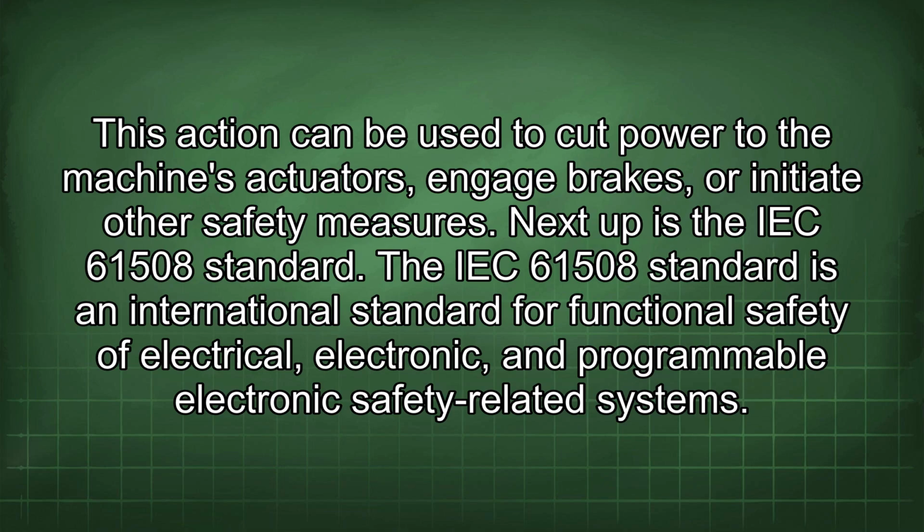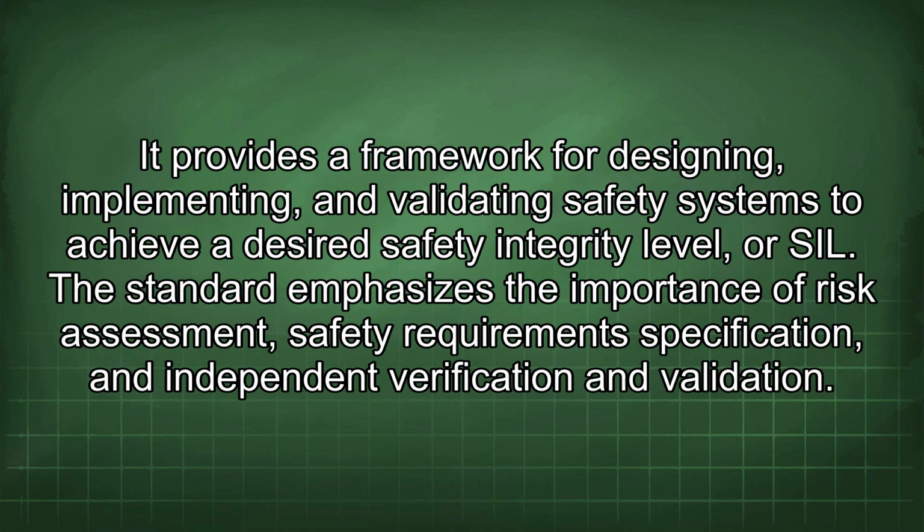Next up is the IEC 61508 standard. The IEC 61508 standard is an international standard for functional safety of electrical, electronic, and programmable electronic safety-related systems. It provides a framework for designing, implementing, and validating safety systems to achieve a desired safety integrity level, or SIL. The standard emphasizes the importance of risk assessment, safety requirement specification, and independent verification and validation.